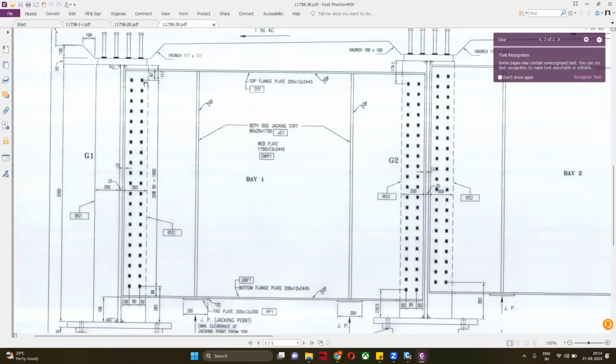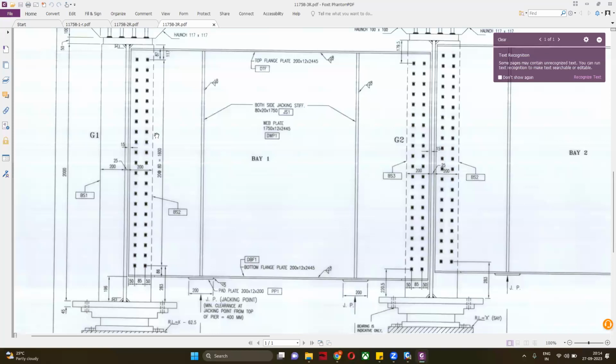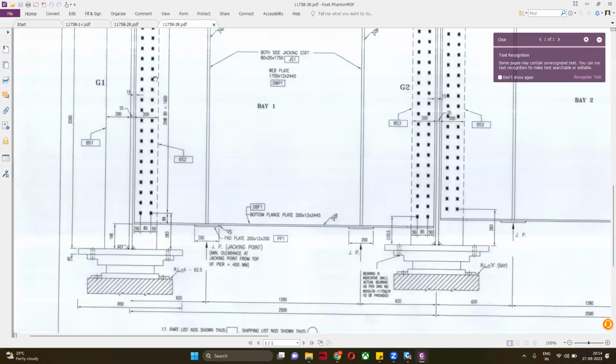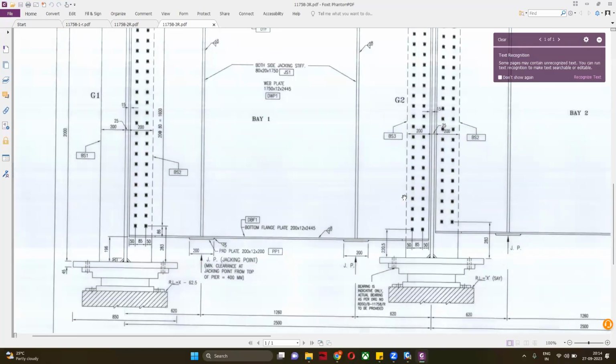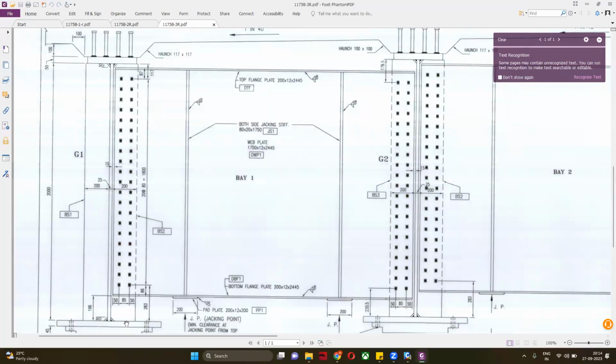And if you look here, this is not even connected with our slab. This is connected only with the web. So what does that mean? If my end diaphragm is only connected with the web, this is a shear connection. This is not a moment connection because the flanges are not connected, so moments are not going to be transferred between them. Now, from where do I need to provide it? I can provide it from the mid portion directly. You do not need to create any other.